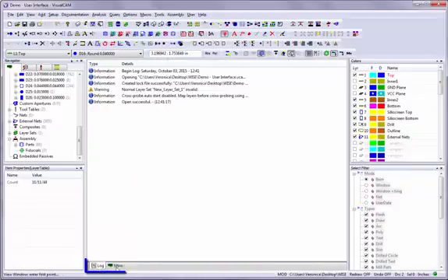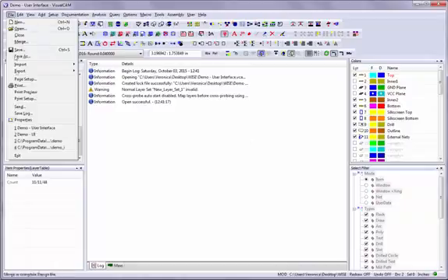At the bottom of the workspace are the View tabs. The default tabs are Log and Main. Log shows a record of all of your actions since you opened or created a database and is cleared when you select the File New or File Open command. To save the log as a file, right-click in the log screen and select Save Log from the shortcut menu, or select the File Save Log command.